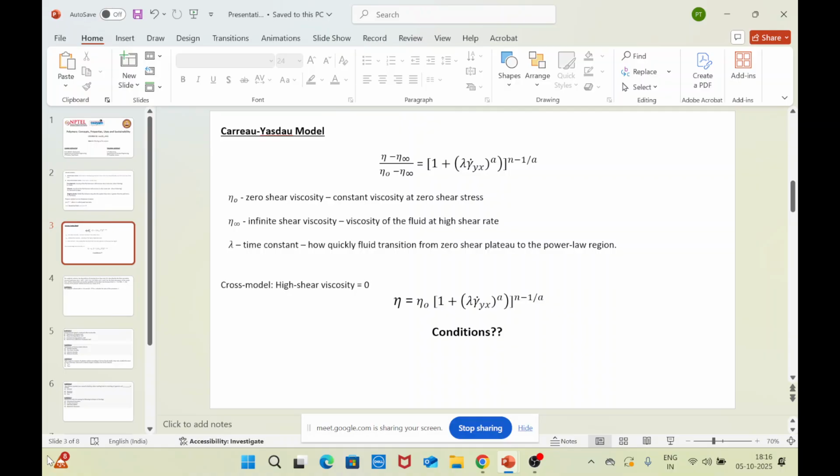Since a network structure is formed, the rheological behavior will vary distinctly. As per the Herschel-Bulkley model, they exhibit something very similar to what we discussed about the Bingham plastic right now. In that particular model, it is described that since the polymers actually form networks, as you add nanofillers, the major reason you do is to form a network structure so that the crosslinks will be more in those cases.